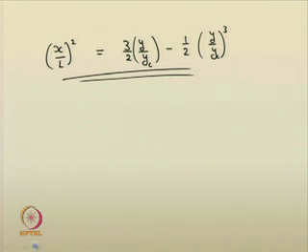Some scientists have tried to obtain this. If you recall, in gradually varied flow we had well distinguished flow profiles, say mild slope, steep slope, horizontal, adverse, all those conditions were incorporated and we had various kinds of gradually varied flow profiles. Unfortunately, in spatially varied flow, well defined categories are very much limited. Only very few scientists have worked on that and they have come up with certain strategies. For example, the scientist Lee in 1955 performed certain analysis on spatially varied flow.